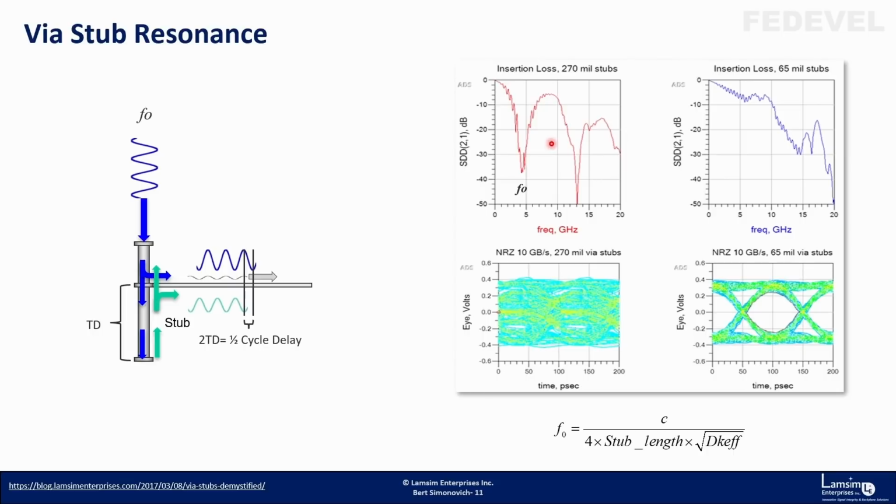Okay, so this is an actual measurement with S parameters. This is a measurement of a backplane channel or structure, and it had a stub length of 270 mils. It uses a vector network analyzer, or VNA, to get the S parameters. And it sends all these different sine wave frequencies, right up to 20 gigahertz here. So each point is a certain sine wave frequency.